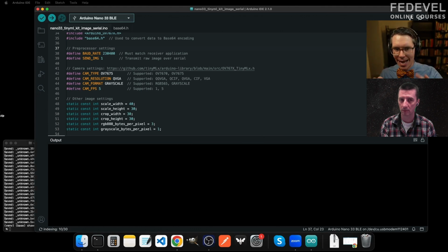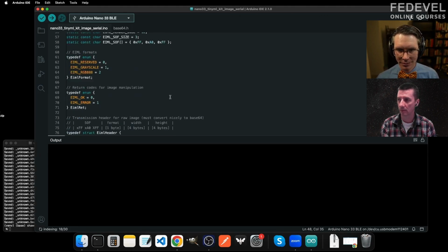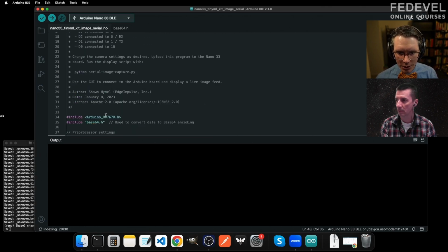The next one is doing static inference, where you take a known good image, you feed it through that classifier, and you compare it to the answer you get, say, on Edge Impulse or your TensorFlow library. I always do that prior to writing live inference to check that my classifier is working the way I intended. For DSP, you would do something similar, right? I use MATLAB or Python and I created my DSP function, I created my filter. Great. I'm going to rewrite my filter in C or C++, and then I'm going to give it a known good input and make sure it matches the output with my high level language. Same idea.